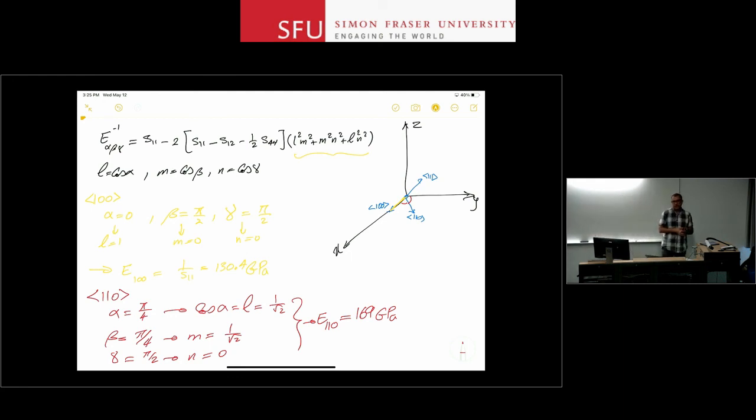This actually is your typical orientation for most of your beams. The reason for that is that, in the old days when we had wafers and the wafer had flats, the flat indicated the 110 plane on a 100 wafer or 111 wafer. And then what you did is that when you were doing the mask alignment, you always made sure that this flat is aligning at the bottom. Let's say it's parallel with the edge of the mask.